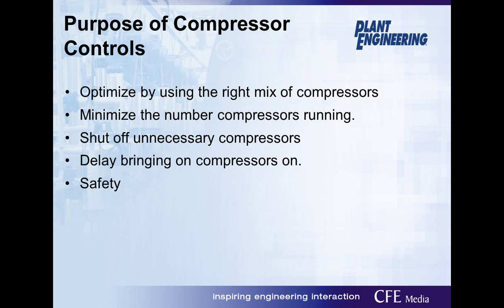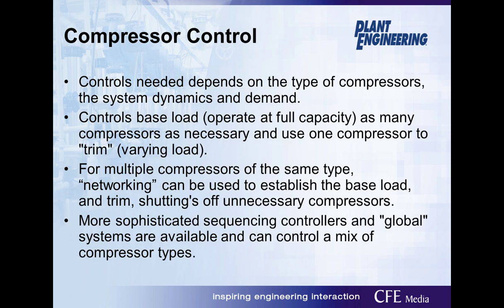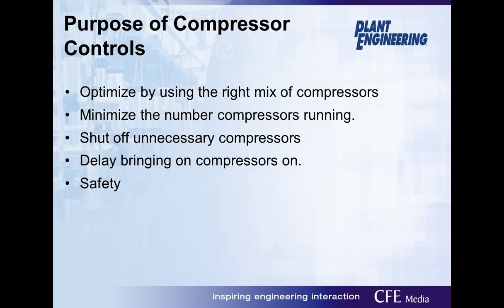So one of those ways we do that is going to be through compressor controls. Now, compressor controls, really the reason we want to do this is to optimize the right mix. Again, number of running ones, shut off unnecessary compressors, delay bringing them on, and of course, another big piece of that is safety.